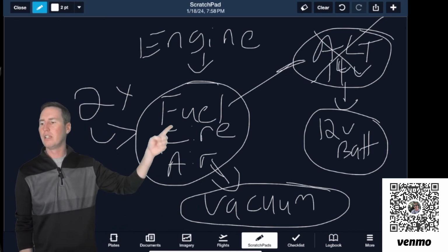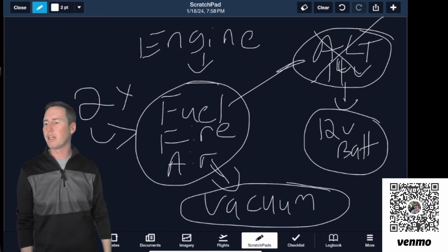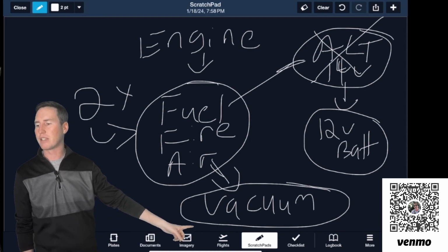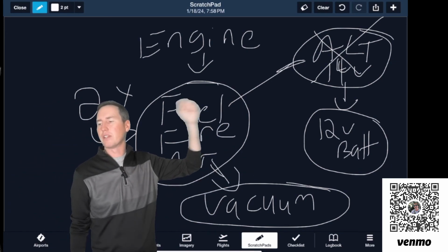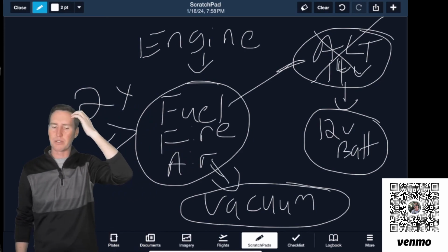We only have one engine. Our redundancy is built in the fuel, fire, and air that we talked about. We have a vacuum pump that's attached to that engine, which we'll talk about in the next video, and then our alternator is our electrical system.